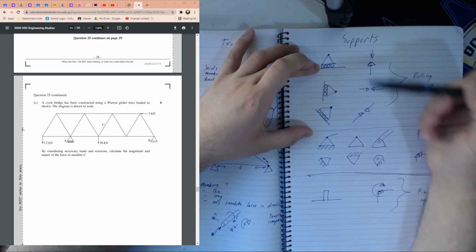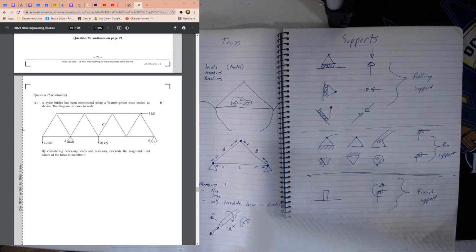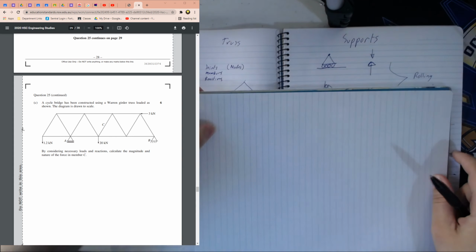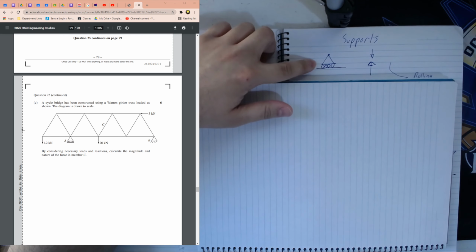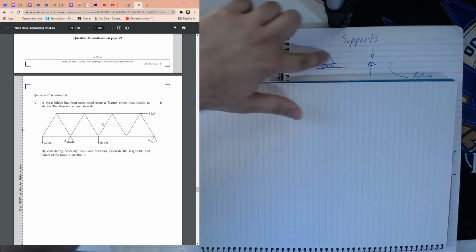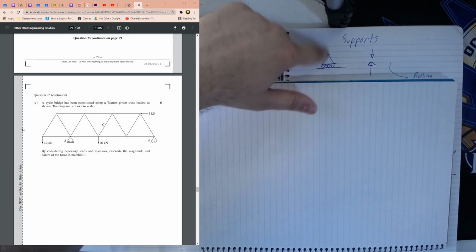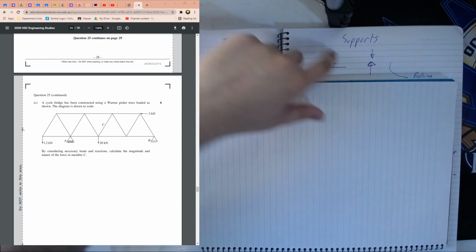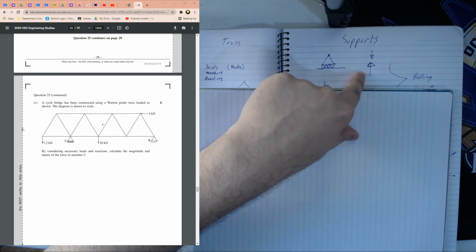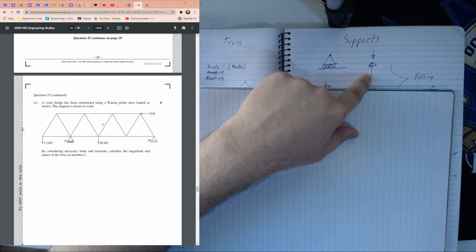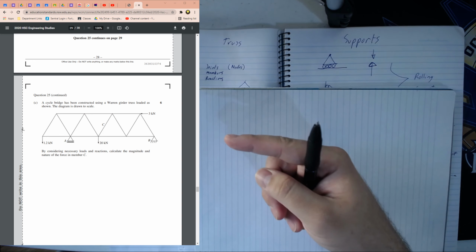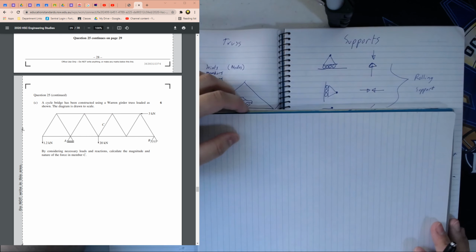Same thing over here with this bridge. In this first support example over here, actually this way is better. This over here is a triangle with the rollerblades. This support is able to move left and right very easily, but it is going to be providing a force onto the structure in the vertical. So that's why this particular rolling support provides a reaction force in the vertical. And as we see, this is the same one that we have in our HSC question at point A.